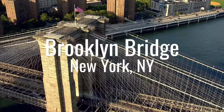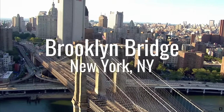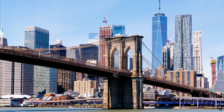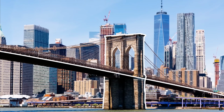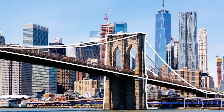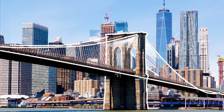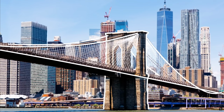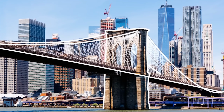Can you combine these different bridge types? Yes, so the Brooklyn Bridge is a good example of a hybrid between a suspension bridge as well as a cable stayed bridge. So you have your very, very large towers, your pillars, your piers that have existed for a very, very long time that have these draped cables from one to the other. From these draped cables, there are vertical cables that are attached to the deck, as you would see in any other suspension bridge. But if you look very, very closely, you will also see that some cables are at a diagonal. They're also attached from the deck directly to these tower piers, which makes it more of a hybrid between your suspension bridge as well as your cable stayed bridge.